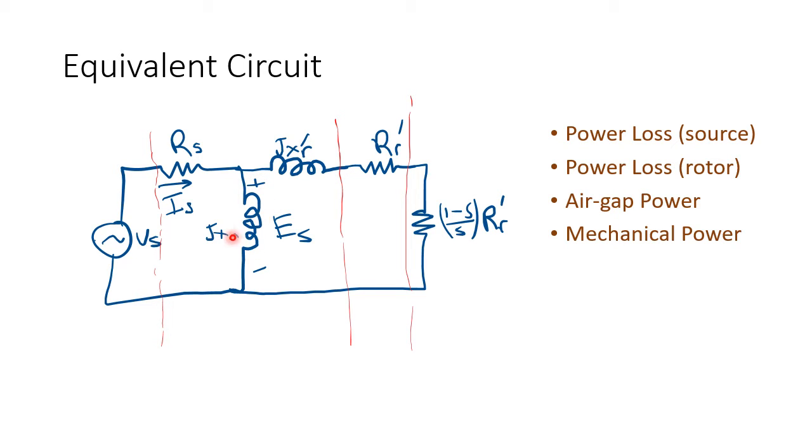So we're going to call this XM, so the magnetization current. And so you'll notice when you turn it on, this inductor will charge up, but then at a constant current, when the current wouldn't be changing, the average current is not changing, it's gonna stay. It's not gonna take any power in. So that's equivalent of charging your core, like magnetizing your core. And once it magnetized, it wouldn't do anything within it because you already established your magnetic field.